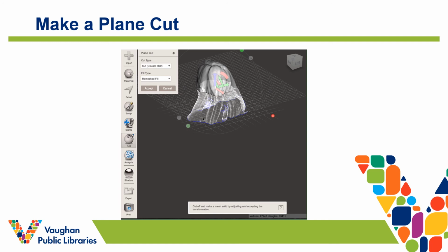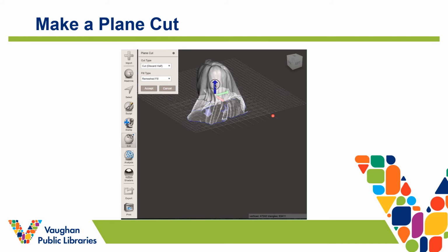Here's where you will get to decide exactly where to cut your item by moving the blue arrow up or down, which moves the grid. Whatever is below the grid will be removed from the design. Once it reaches the desired position, click Accept.